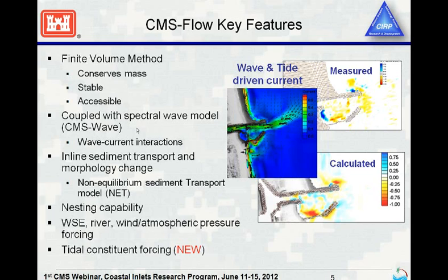It's coupled now with the Spectral Wave model, CMS-Wave, that better handles the wave and current interactions so that your waves can modify the currents and vice versa. It has an inline sediment transport and morphology change. We've implemented a non-equilibrium sediment transport model, which is a little bit different than how we've always done it, but it makes the answers much more reasonable and hopefully easier to get the right answer.